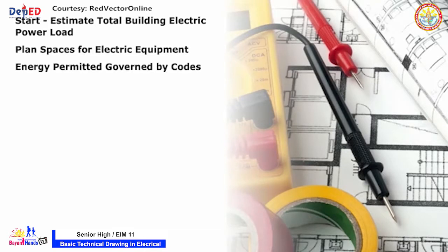The amount of energy that a building is permitted to consume is governed by building codes. A building energy consumption analysis determines whether the building design will meet the target electrical energy budget. If not, the engineer must modify the electrical loads and reconsider the projected system criteria.